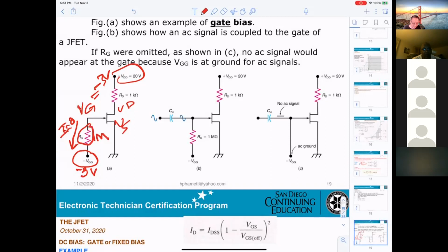I can do without it. I can connect directly here. Same thing. You can connect minus 3 volt directly to the gate. However, Mr. Pham, just real quickly, are you saying that the resistor is so big, the current is zero, so it's almost like the resistor is not there and it's just directly connected to the -3? Right, you can connect directly to the gate from -3.